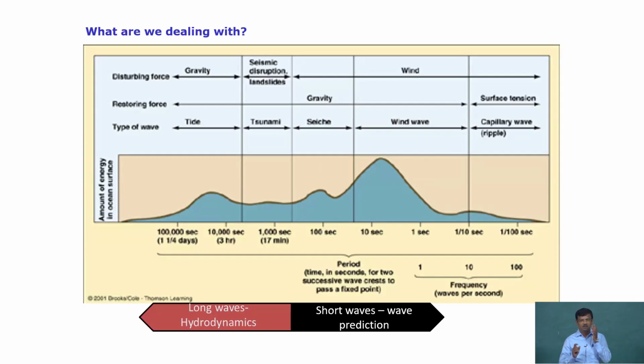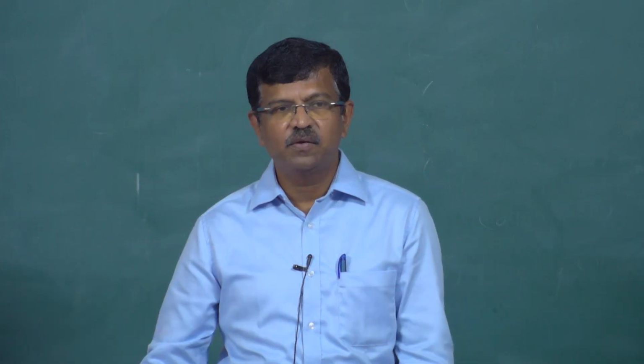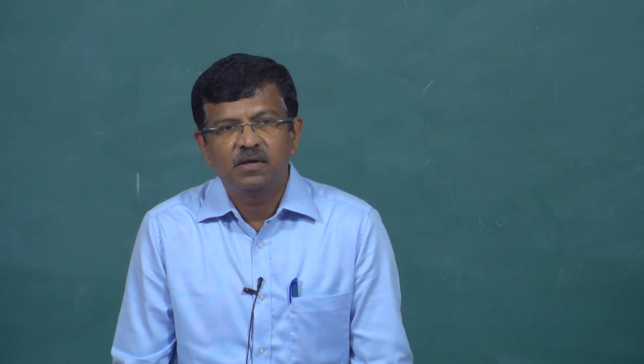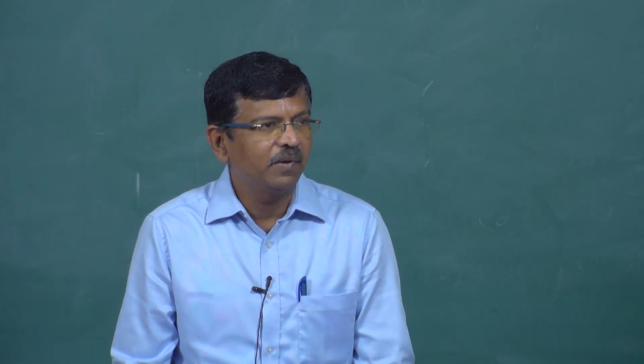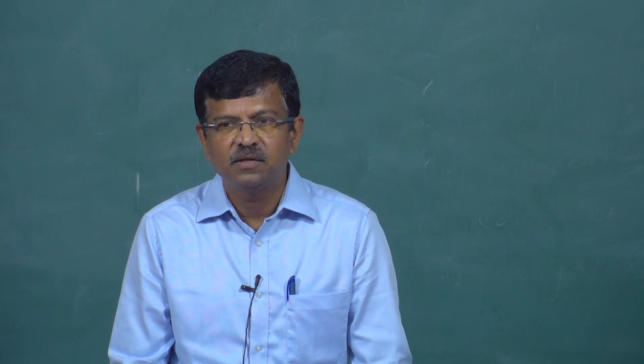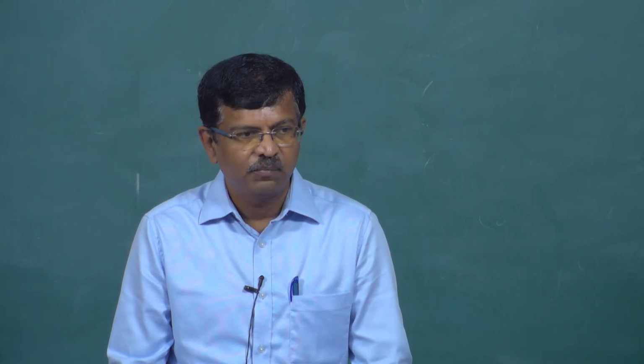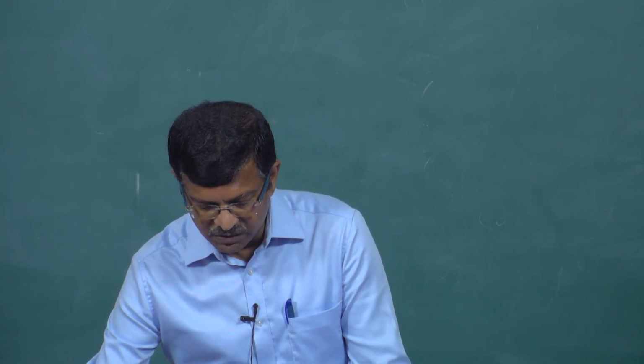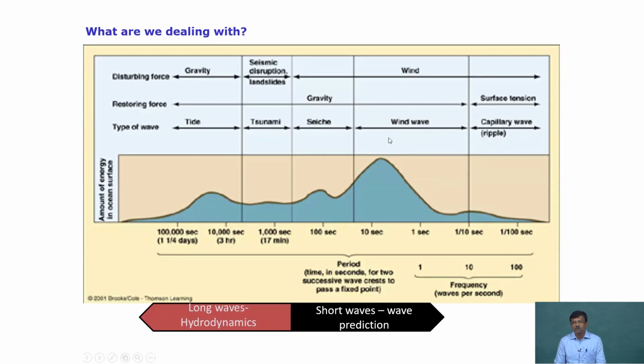The waves at the open ocean are going to drive a lot of sediment from one point to another, because the entire energy content is there. That is one of the reasons that for most of our sediment transport, one of the major driving forces is the ocean waves, which are the wind induced waves, of 5 to 15 seconds or 5 to 20 seconds of that range.